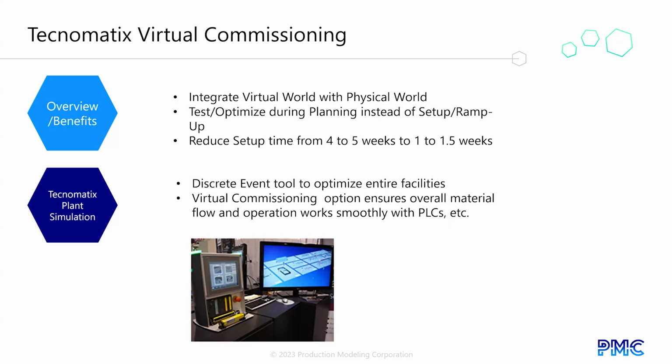One of my clients used this to check that the PLC control logic worked for their factory's conveyor system, which had numerous light sensors and stops along the way where parts would wait for certain conditions before moving on. They were especially concerned about an interesting past problem where a standalone plant sim like discrete event simulation showed that their control logic worked.